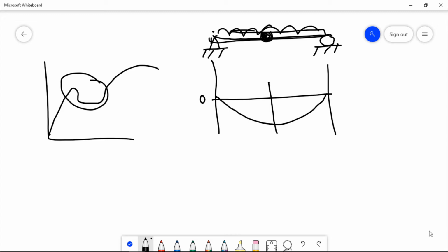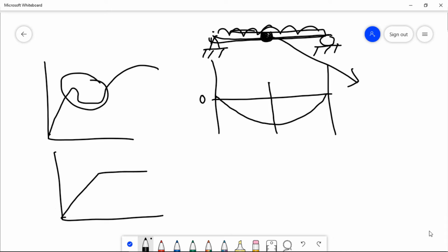This point where yielding occurs is called a plastic hinge. The yield point is in the plastic range, because we use a simplified bilinear curve. Now this is a plastic range, so that's why this point is called plastic hinge.